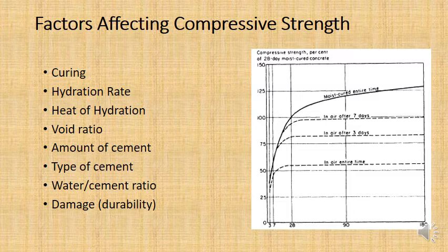If you have too much cement, it will make the concrete weaker. What you need is enough cement that it fills the voids between the aggregate particles if they were sitting well compacted. The type of cement can influence the compressive strength too.